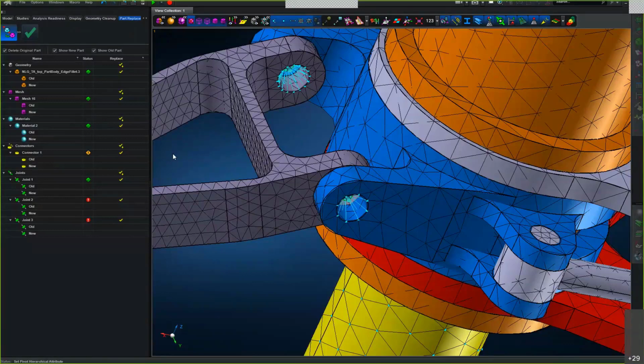We will be adding seam connectors for things like seam weld. But these ties, the mesh dependent tie and the mesh independent tie, are just numerical tricks to join meshes together where you're not specifically modeling the fastener. Yes, so mesh dependent tie and mesh independent tie is just glue.